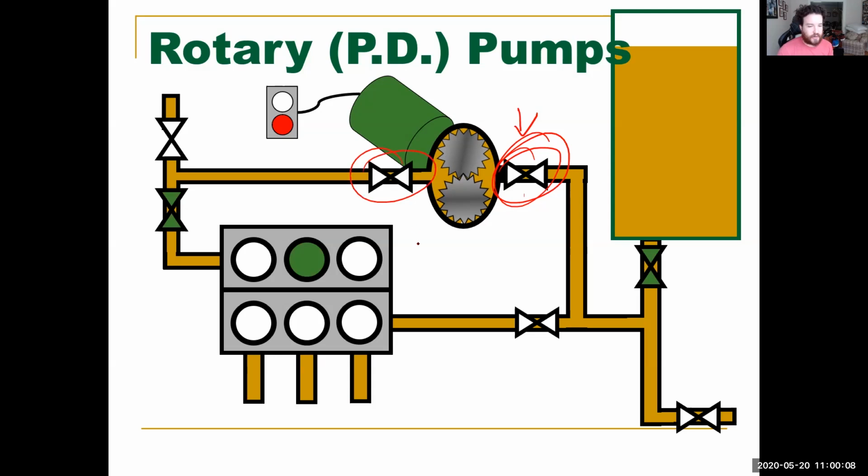Close your inlet so you know your pump's secure, and then go through the rest of your system and close all your valves. Always secure your valves. You don't want to be in a situation where you're pumping from another location and all of a sudden now you're sucking from somewhere else as well.